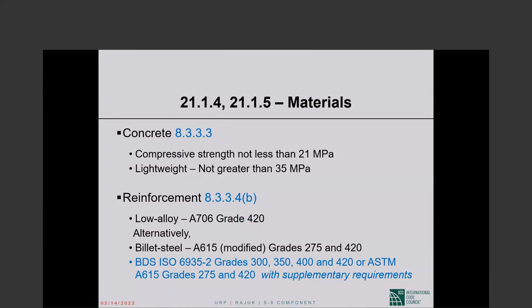I still included them in this slide set so that you have a complete slide set for shear walls, but I will go over them kind of quickly. Okay, so normal weight concrete, no upper limit on the compressive strength, but the compressive strength cannot be any lower than 21 MPa,